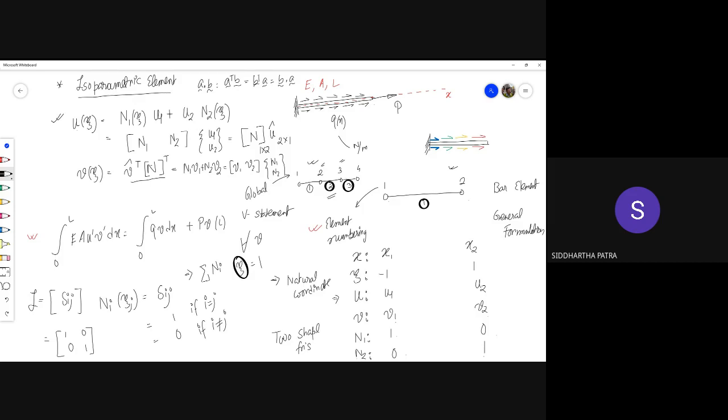It's not really my choice, but it could have been my choice. That's the one that I'm implying here. So it helps in formulating the expression of shape functions. I mean, I could have also taken 0 and 1 and gone with it, but later on when we write the expressions for the shape functions, that's when you'd see that -1 and 1 kind of works.